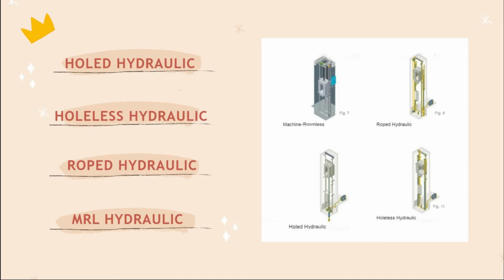Next is rope hydraulic. Rope hydraulic elevators use cables and a piston attached to a shaft, as in a standard holeless hydraulic elevator. Since a rope is holding up the elevator cab, a governor is required. These models are intended for 60 feet of travel.